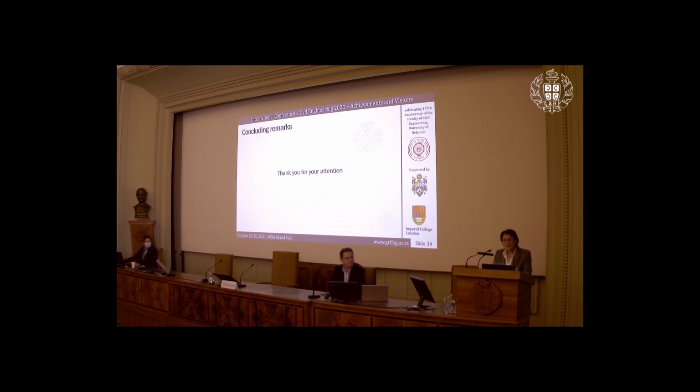When we conduct our testing, we do take specimens of soil from various depths and from various locations on the site. So yes, from the few graphs that I showed of the soil data, you will see that there are a number of lines. And yes, we do have to perform interpretations of what we believe is the best estimate of strength, of stiffness, and so on.